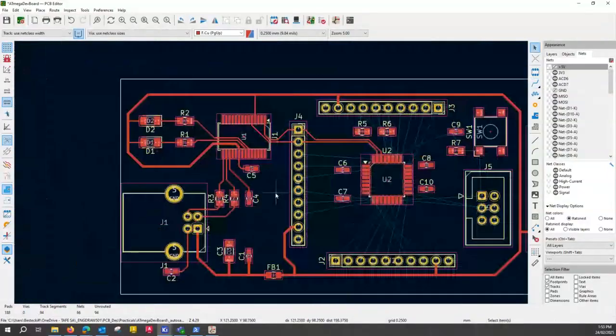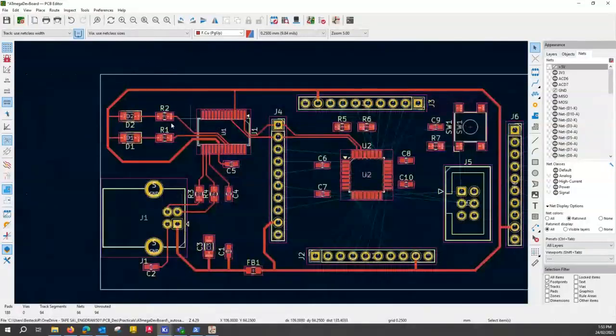So as you can see, we've got this part of the circuit on this side completely connected with no crossing to the other side. We've got no lines crossing, nothing is crossing, everything is good. So you always try to save this. You always try to route it out so you've got all direct connections, you don't have any lines crossing, you don't go under the board, over the board, and do all sorts of tricky things to cross those lines. We'll have to do them in here, but we didn't have to do it in there.